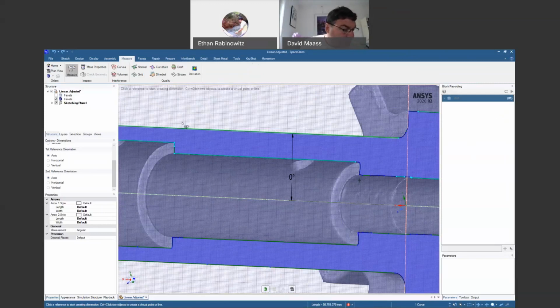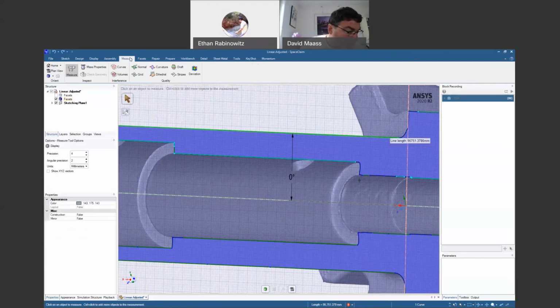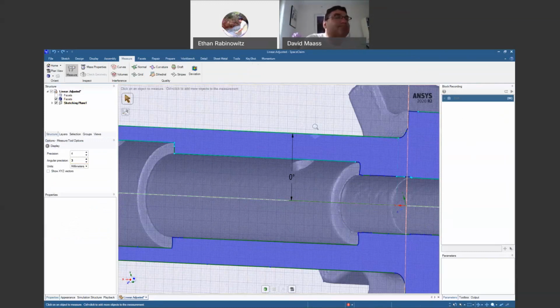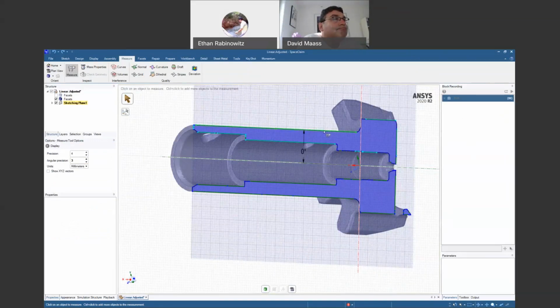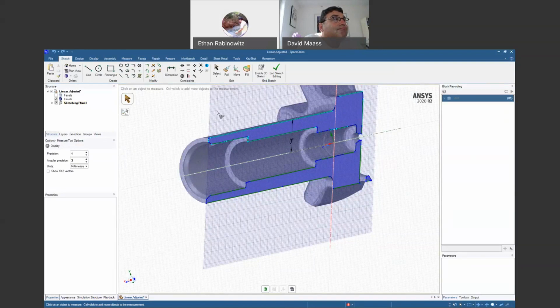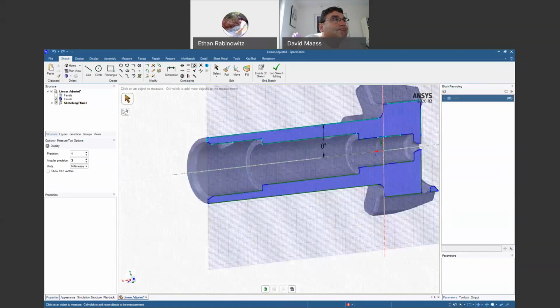Okay. But one thing I could do here, I could use our measure tab and measure tool and just take a quick measurement across here. Rounding, it's still 0, but in this options panel, angle right there. So yeah, it's like 0.003 out. So extremely close. If we don't address this, we will get a cone at a slight angle. And that is where the new sketch solver and sketch constraints comes into play. Because we essentially have a tool for that.